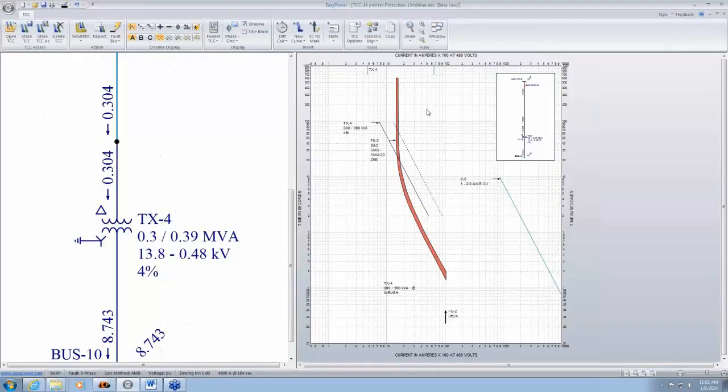The fuse shapes have such characteristics that it's impossible to get all the desired settings to protect the transformer fully. In the case of relays, and you would have relays protecting transformers only for large transformers, you might be able to get a greater variety of settings to closely protect the transformer against mild overloads as well.